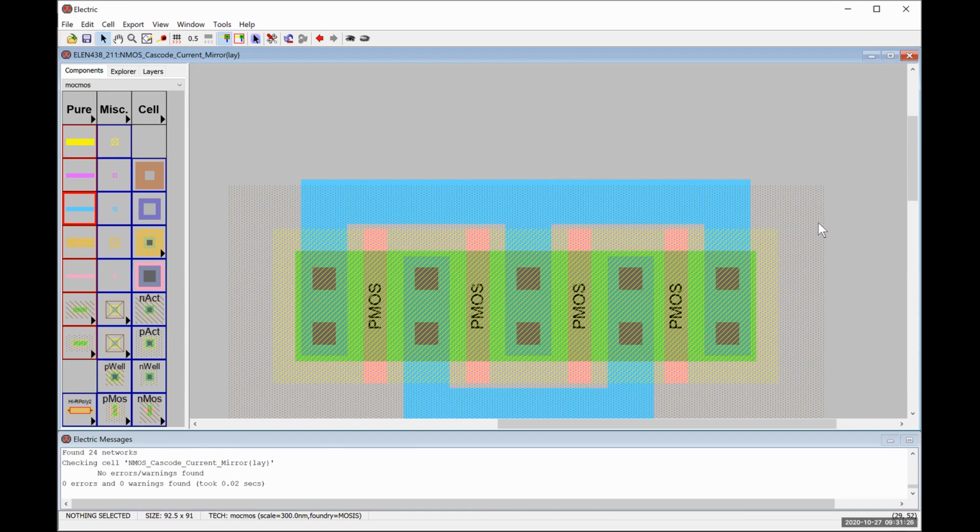All right, so one important thing here is that we all need to agree that this is a 30 by 2 transistor. And I know I don't have the gates tied together. I'll do that momentarily. So the reason why I'm calling it a 30 by 2, even though it is 4 transistors, is again because this width region from here to here is 10 plus another 10 plus another 10, all in parallel makes 30. So we should be good to go there.